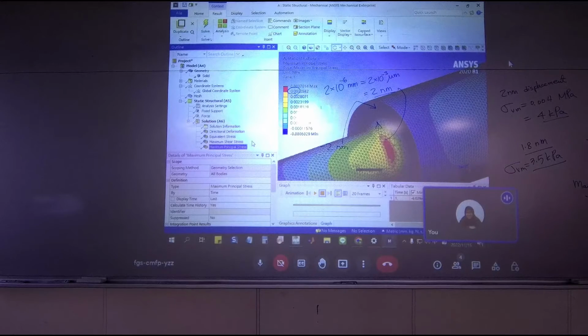If you use normal stress, then your normal stress needs to be smaller than your yield strength over safety factor. So at the end, you have the same model. These two are the same. But how about von Mises? If we use von Mises, then it's a little different.